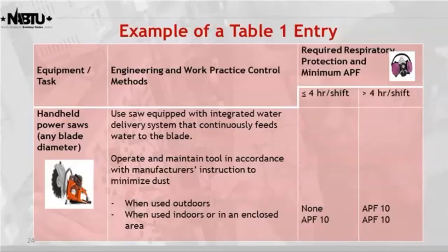Generally all the newer saws, like you see here, come equipped with an integrated water system. So there's basically a nozzle on the bottom that you hook up a garden hose to, and it maintains water on the blade as you're cutting a unit. Notice that this particular saw would be designed to be used with water, whereas an electric one may or may not be because of electrocution hazard. Most electric ones may come with a vacuum system, some sort of suction device in order to limit the dust and fly.